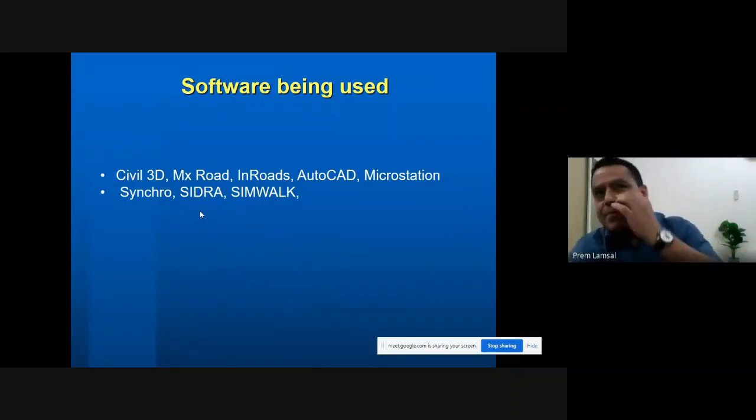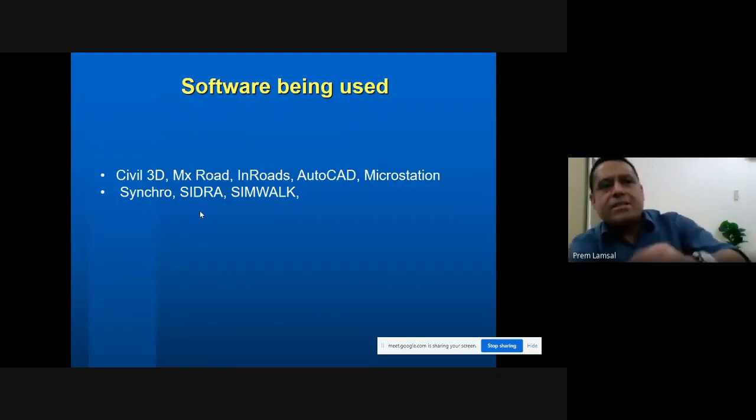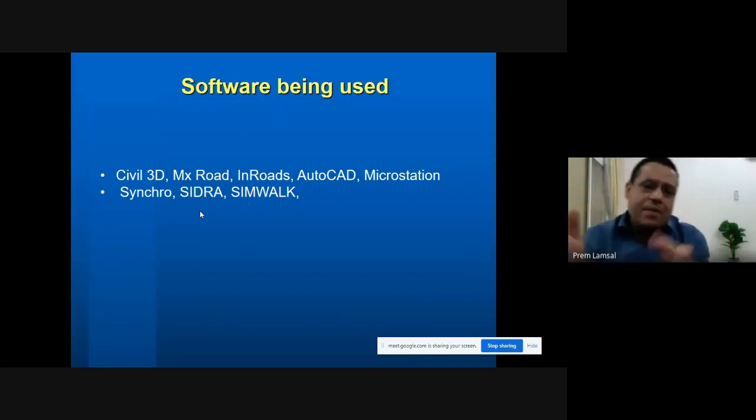Normally standards are the same. In the Middle East, the minimum width of a sidewalk is 2 meters, as specified by the guidelines here. For example, the Qatar Highway Design Manual specifies a minimum sidewalk width of 2 meters. If I cannot meet this for some reason during design, I have to request a variation: I'm not able to make this 2 meters because of this reason, and I'm providing only this much.